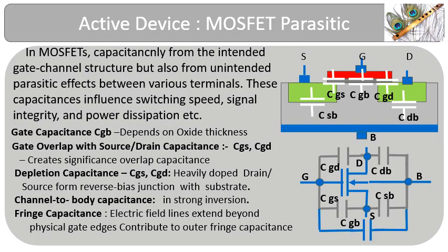Let's review the MOSFET transistor capacitances. The thin gate oxide layer forms the primary gate capacitance. But parasitic capacitances also emerge between gate, source, drain, and body terminals. The gate has both channel coupling and overlap capacitance. The CGD and CGS are gate overlap capacitances.